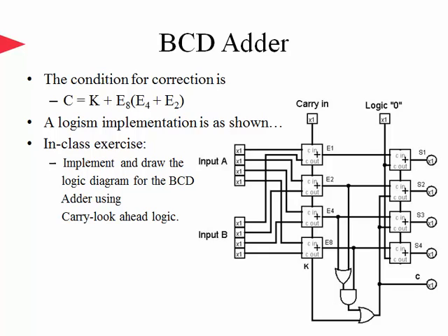You can also use 7-segment displays for debugging purposes. When you experiment with the BCD adder in Logisim software, I highly recommend that for you. The BCD adder is implemented using full adders. If the application is delay sensitive, we may replace the cascade of full adders with a binary adder that's based on carry look ahead logic. It is left as an exercise to implement the same circuit using carry look ahead logic.